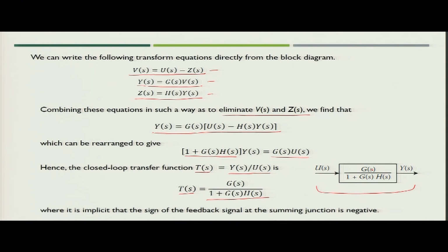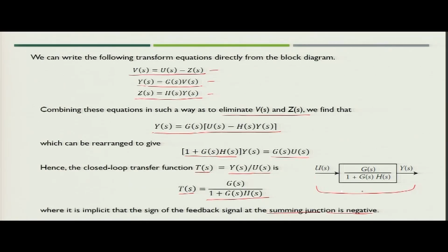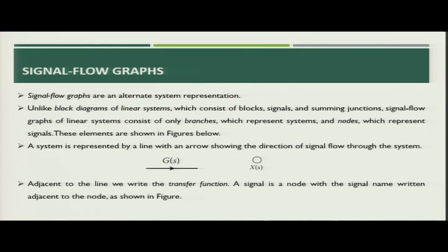is the output. Now, here in this case we can observe in the previous figure that the summing junction will have a negative feedback signal. So, here we have added negative as a feedback signal to find the Laplace transform of the complete feedback system.